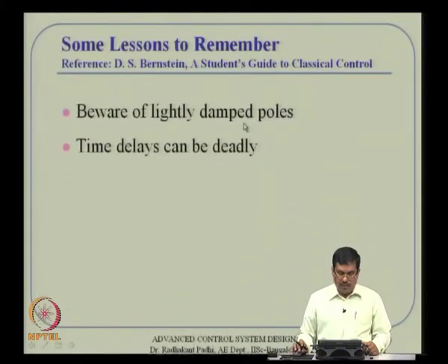We also have to be worried about lightly damped poles, because they cannot be rejected so easily. The behavior of those lightly damped poles has long-term effects. Remember, they are close to the imaginary axis. That means there is a danger that these poles may go to the right half plane and the system becomes unstable after that. So you have to be very careful about lightly damped poles close to the imaginary axis.